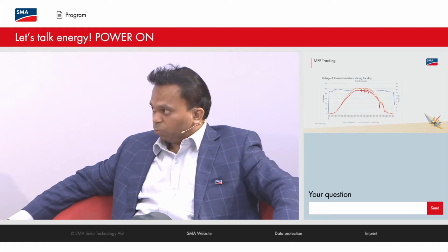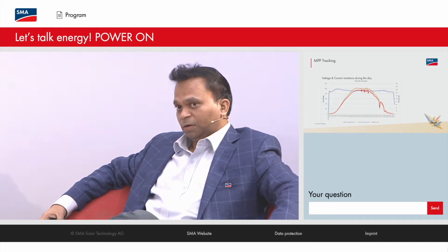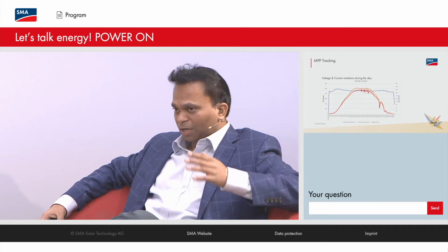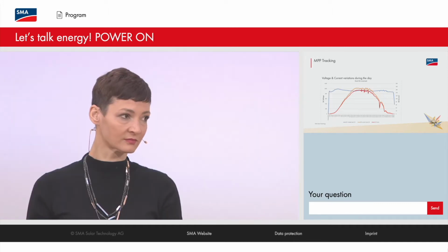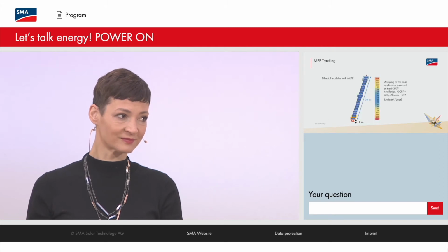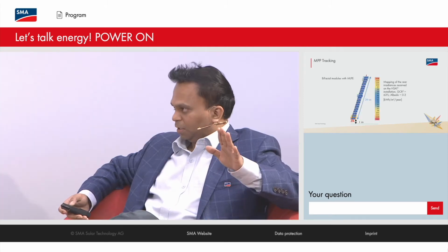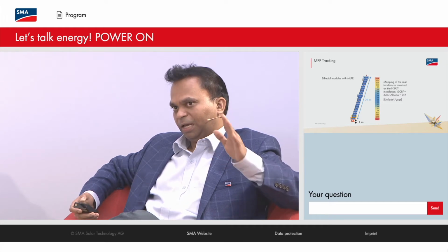Some advantage, I would say, out of this multiple MPPT is a marginal increase in yield, but it's so marginal that in an oversized field, it makes not much of a difference. And if this is not sufficient, let me go to an extreme example.